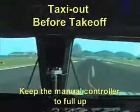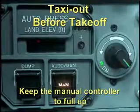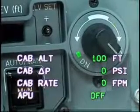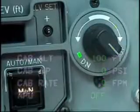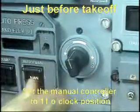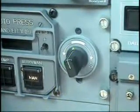Taxi out before takeoff. Keep the pressurization manual controller at the full up position. This setting will make the cabin altitude remain stable during taxi, independently of any variation in bleed. Just before takeoff, ensure the manual controller is set at the 11 o'clock position. This position will guarantee an acceptable pressurization during climb out.